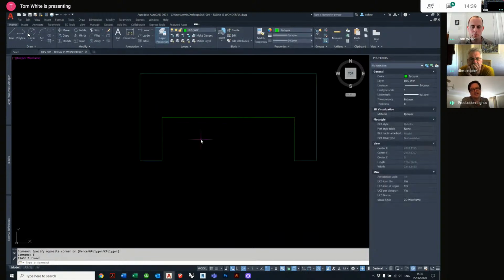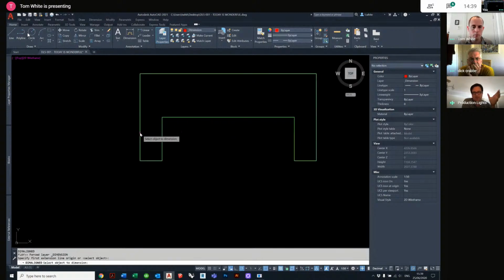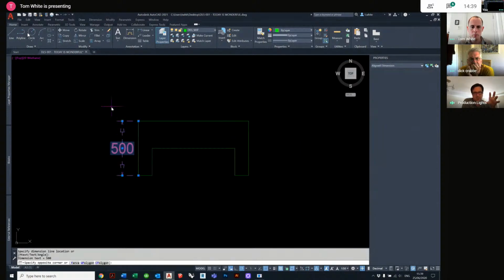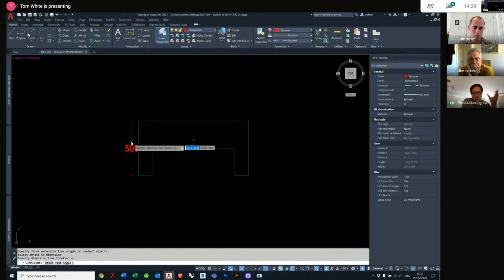So my example is chairs. A lot of the time I will bring chairs into the drawing. I expect you do too, to set up a drawing, and then we get a few weeks down and the lovely people come and say, actually, we're using this chair from this rental company, and it's called this. So for argument's sake, I may have something that's called chair 1 simply, and their chair is called chair 1. When you bring their chair 1 into AutoCAD, it goes, well, I know about chair 1, I'm not going to import it.